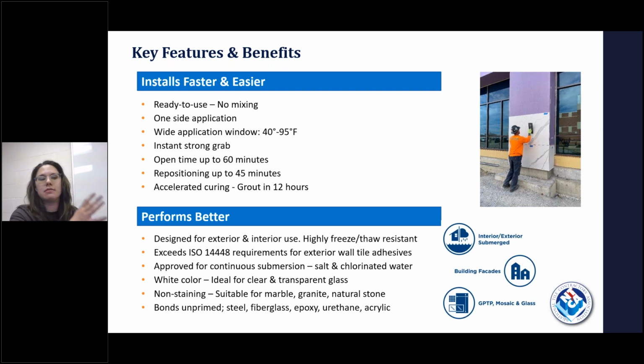It's a lot more forgiving, where with normal traditional cementitious products, you're going to have to be installing between 50 and 60 degrees, right? So that's the difference that you're going to get using these ISO adhesives versus using a traditional mortar. That open time and the repositioning time, all that's written up in the ISO standard, so I'm not going to get too nitty gritty into it.